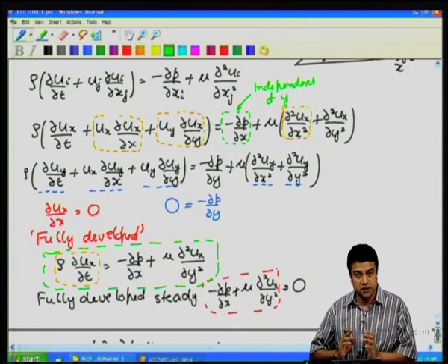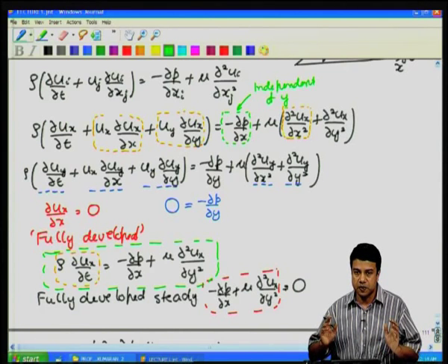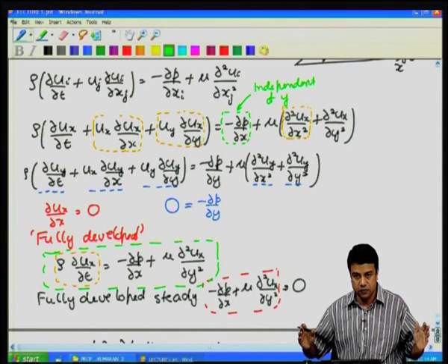One can have such a situation where the pressure is time dependent, but the velocity is not, because pressure travels at the speed of sound. Okay. So, pressure equalizes instantly across the entire width of the pipe at the speed of sound, whereas the velocity in the pipe is usually much slower.